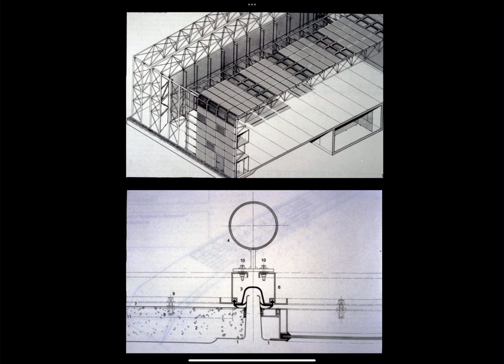It seals the joints between the panels. It works as a movement joint. So the reason that the rubber gasket is curved rather than straight is to allow the building to expand and contract. So this is a movement joint. And the third role that it plays is that each of these joints is a miniature gutter. So this is the rainwater system for the building. There are no conventional gutters and no downpipes and no internal roof drains. So all the water comes off the building in these miniature gutters that occur along the whole length of the building.